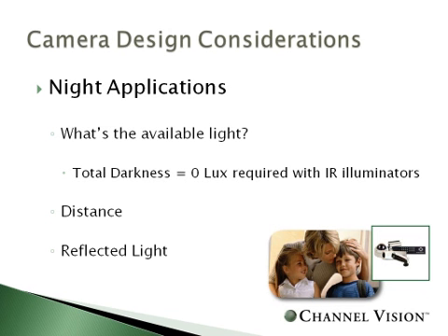How far do you want to see in the dark? Do you really only need to see 15 feet, or are you still trying to cover the entire parking lot? Take into consideration reflected light. Cameras can use reflected light such as infrared repeaters, as well as IR illuminators, or considering floodlight, landscape lighting, porch lights, and the available lighting within the area of coverage.